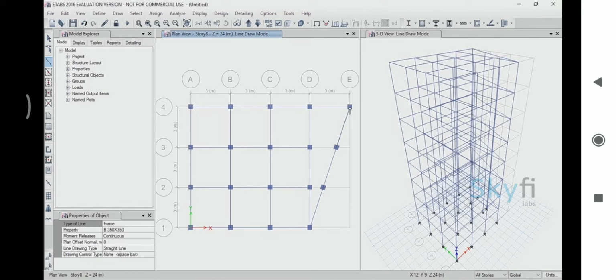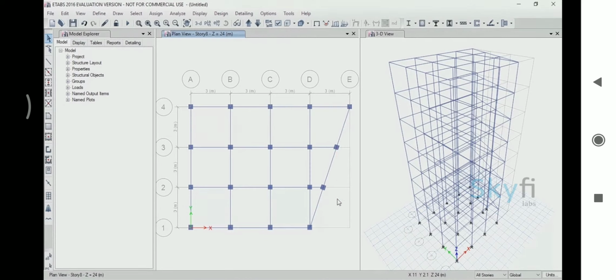After the inclined beams are done, right-click to discontinue the beam drawing tool. Then draw the 2 remaining straight beams individually. Select the 2 endpoints of the beam, and right-click after each beam, to discontinue them. Press Escape after you are done. The beams and columns have been drawn, now you can draw the slabs.